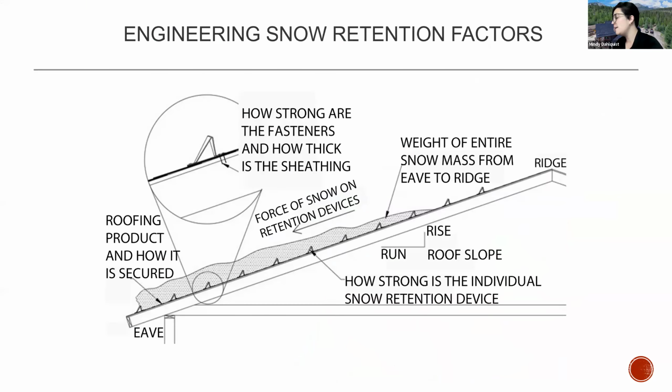So what information is necessary to engineer these snow retention designs or a snow retention system? Some of the information that you will need is: what is the roofing product and how is it secured? How strong are the fasteners that you're utilizing, not just for the product that you're installing, but for the roofing product as well? How thick is your sheathing?